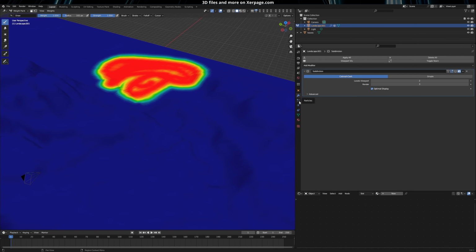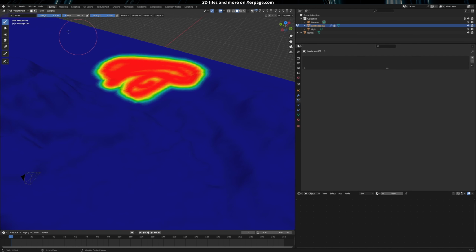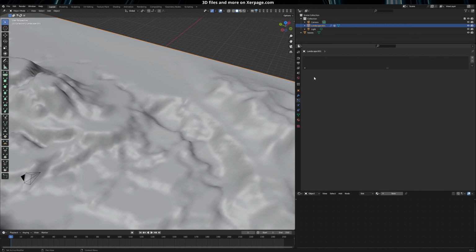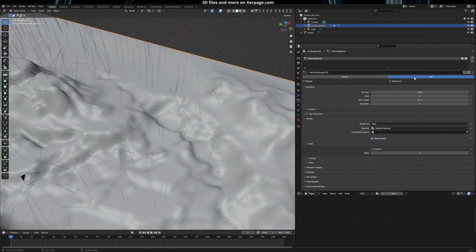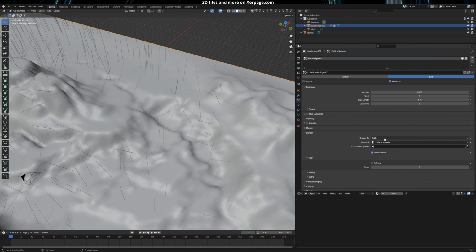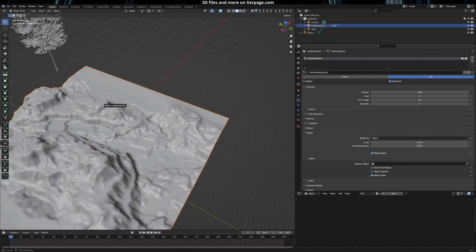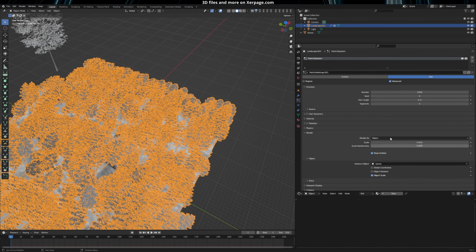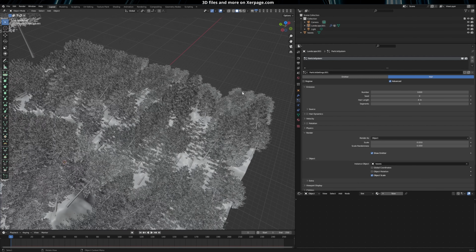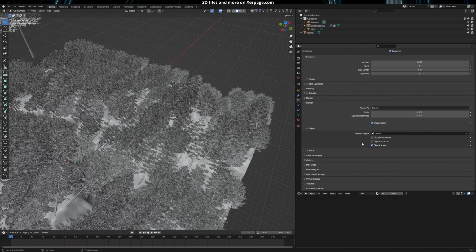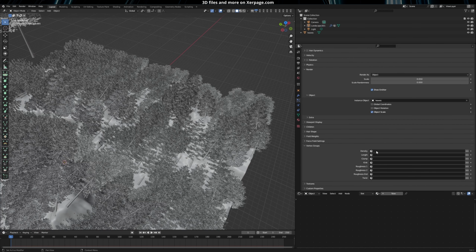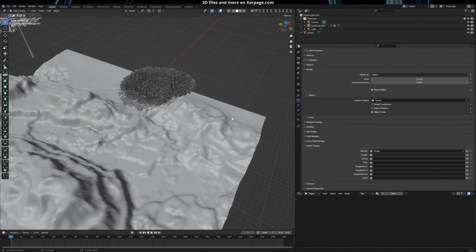and after I go to Particle Systems and go back to Object mode, press on plus, select Hair and Advanced. For the render, use Object if you have only one tree, otherwise use Collection. Go on Vertex Groups and for density, select a group.